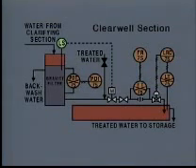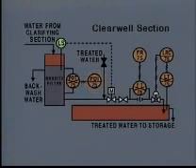The transmitter signal goes to this remote pressure differential indicator. When the difference in the pressures measured at the two pressure connections on the filter reaches a predetermined value, it means that the filter has become clogged by trapped materials.